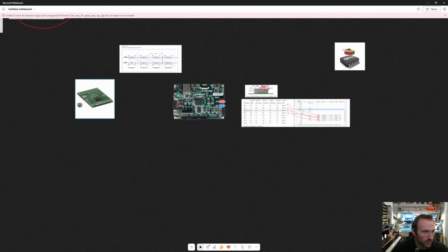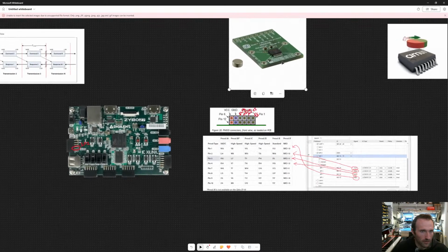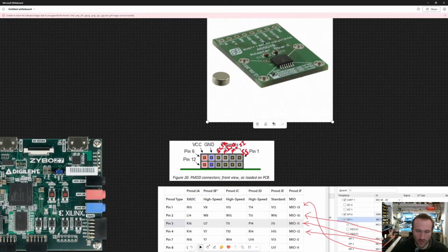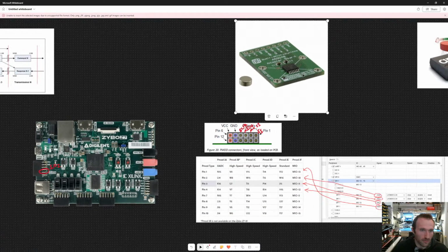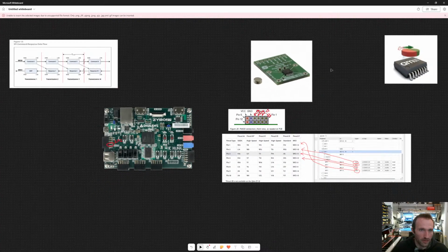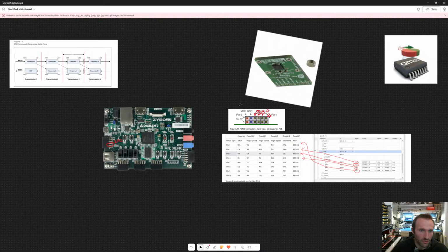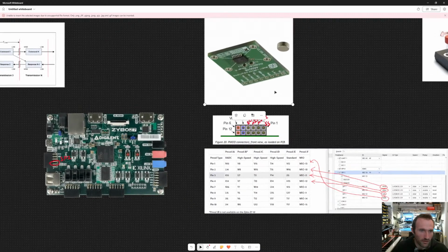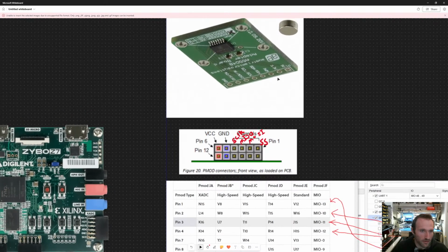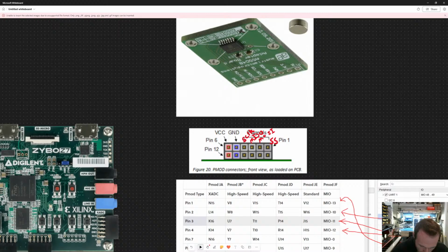These signals are going to be routed to this in that way, right? And then on this silk screen here on the PCB, I'll rotate this. Oh, I can. S clock, right? So that one goes to here. SS, that goes here.